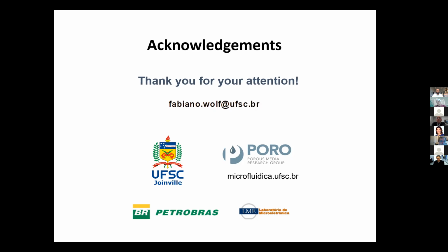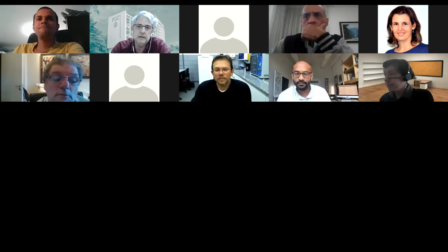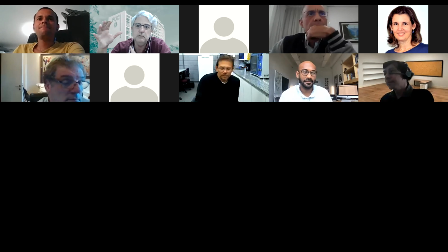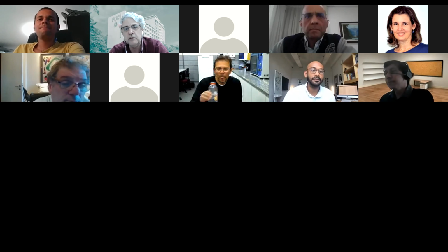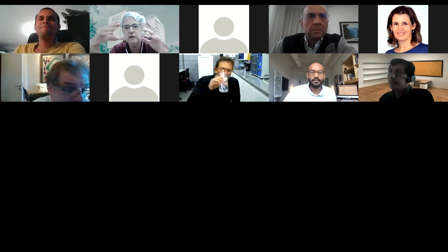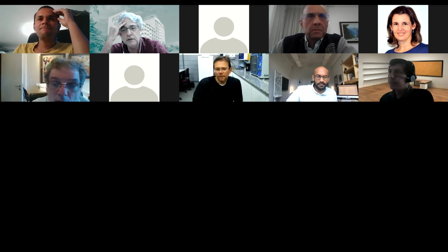Marcia, I have a question. I can start. Yes, Marcia, go ahead. I have a question for Sujit. When you have the pore dependent transition, can you correlate that with the geometry of the pore? What I'm thinking is that if you have a pore where you have a stronger extensional flow, does it go through the instability at a lower flow rate? Can you relate the distribution to the geometry? Because when you show the different pores, it seems that the more extension dominated pores were becoming stable earlier.